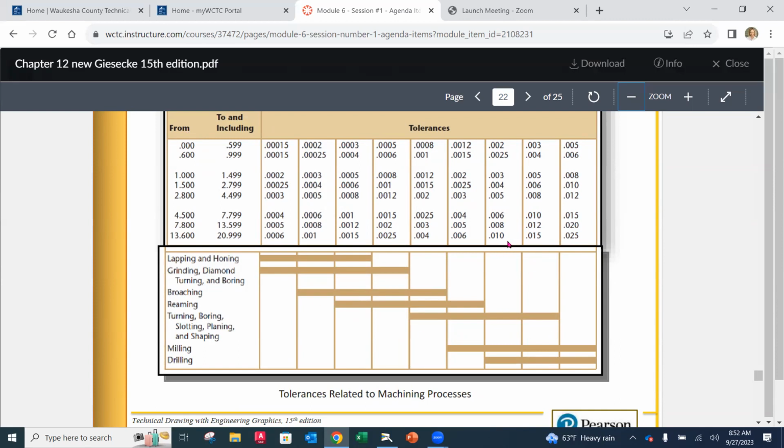The tolerances go up a bit. Okay. So if I'm trying to drill a hole, for instance, that's 5 inches in diameter, the tolerances aren't going to be expected to be as close as if I'm making one that's 1/4 of an inch, which really kind of makes sense. Okay. So that's going to be the range, if you would, that you can get for drilling, but you would want to know the capabilities of the processes you're dealing with.